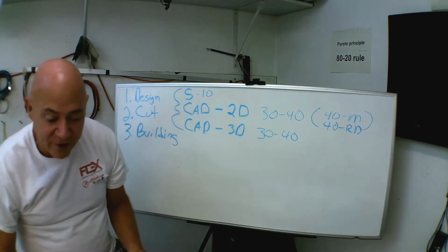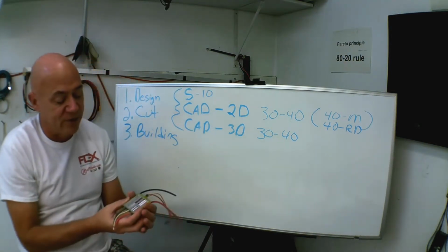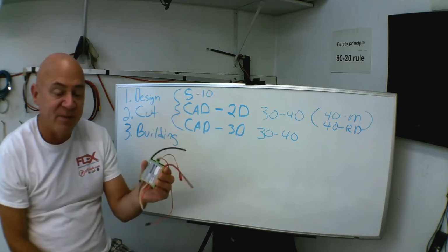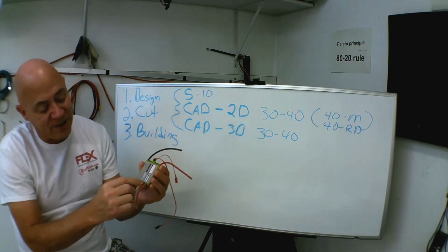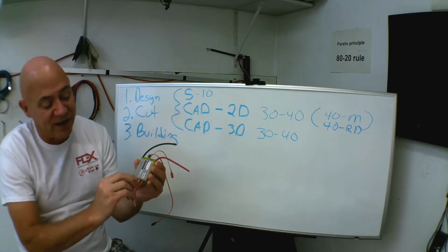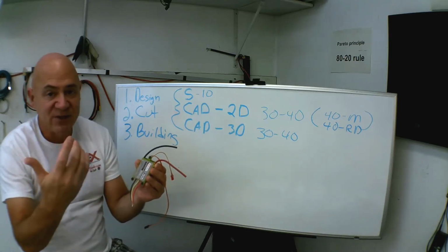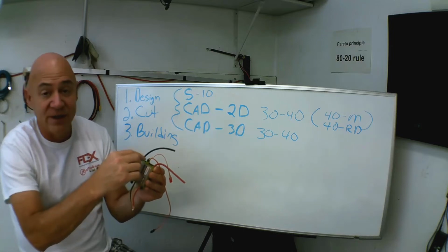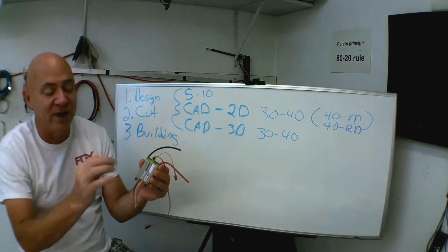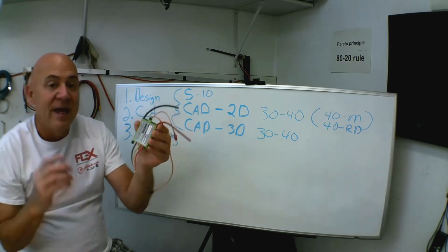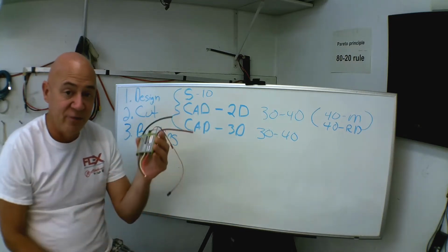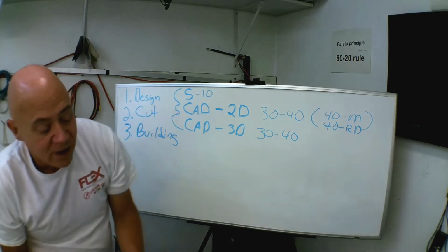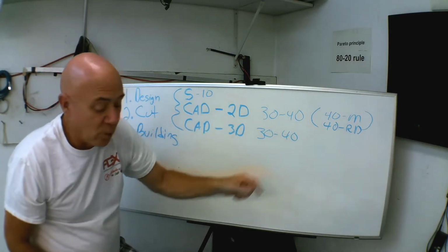Okay? So that type of shit will drive you nuts. It drives you completely crazy because you're sitting here with your calipers, you're measuring everything about this speed controller, and you didn't see that the radiuses of the circles, their edge lined up with the edge of this, and I just assumed when I was drawing that it lined up here, did another 10 millimeter radius, and guess what? It's a 10 millimeter radius, all set 3 millimeters outside of the printed circuit board. What is that? Redesign work.